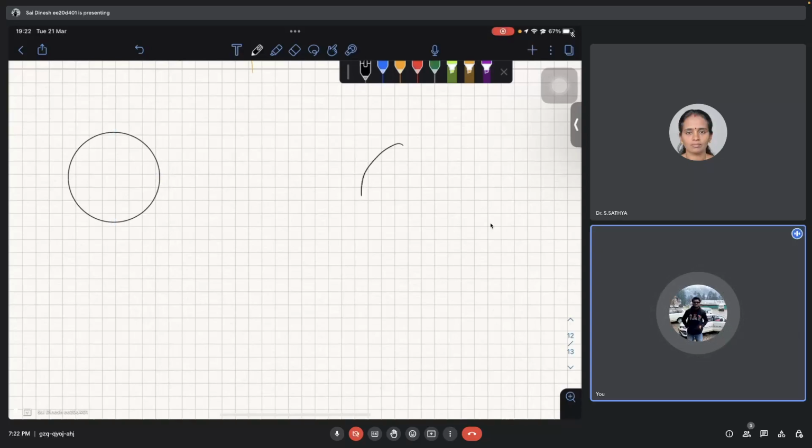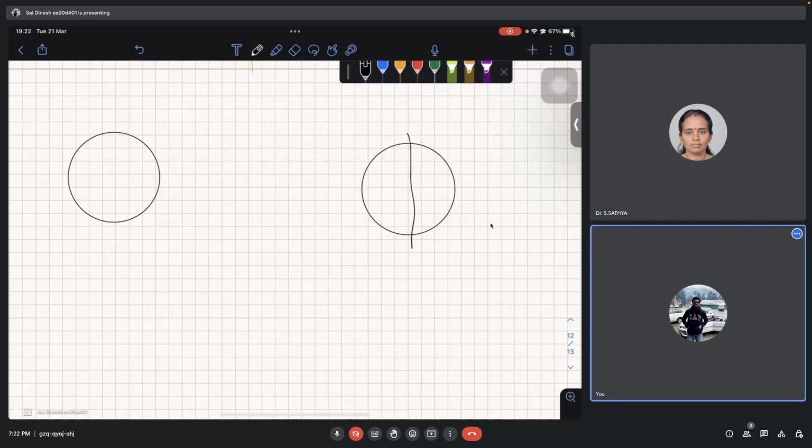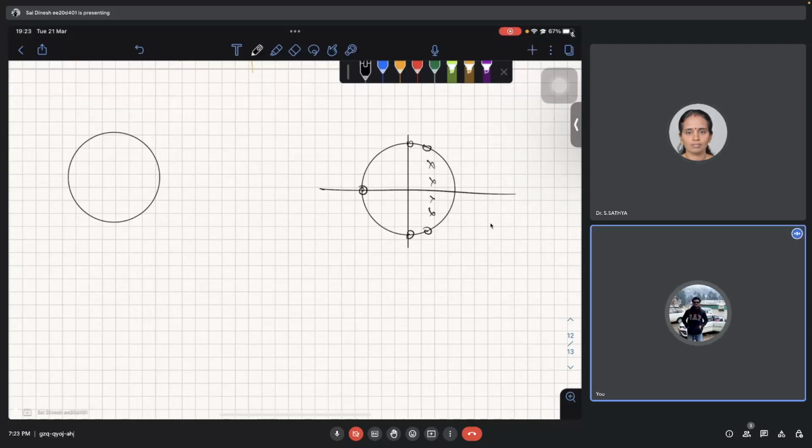Okay, here we have pole zero plots, and a system where there are only a few poles, like three or four, and then five zeros. If we want an FIR filter, we don't have any poles, so in that case the pole zero plot should contain so many zeros.